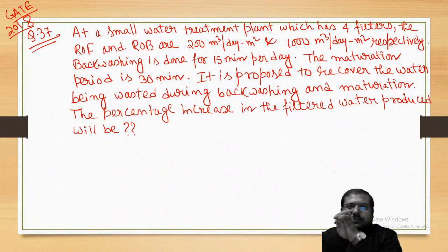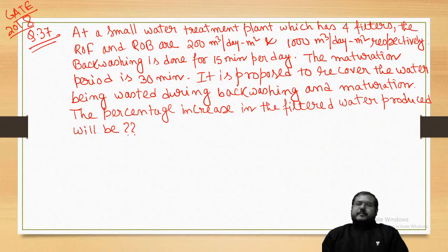Immediately after backwashing, as the filter media is expanded, the water treated will not be of good quality. So what will we do? We give a certain time to the filter media so that it can regain its initial phase. That time is called the maturation period. We have discussed it in the class.